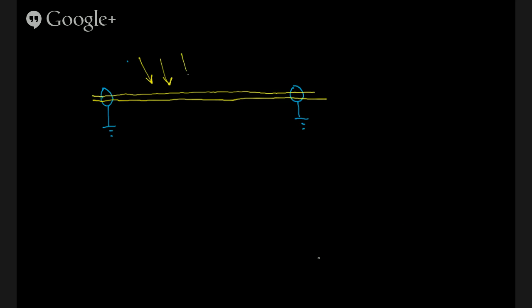Generally, good microphone cables are shielded to help with interference, to prevent signals from leaking into microphone cables, where the conductors inside are surrounded by a foil or a conductive braid, and that will prevent electromagnetic energy from getting into the cable.